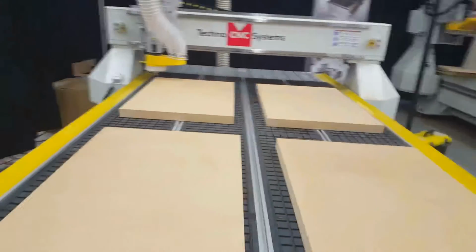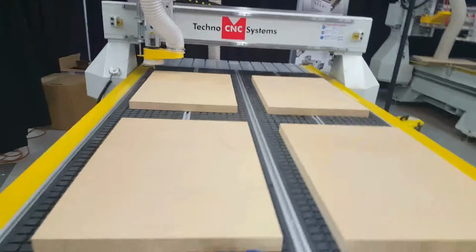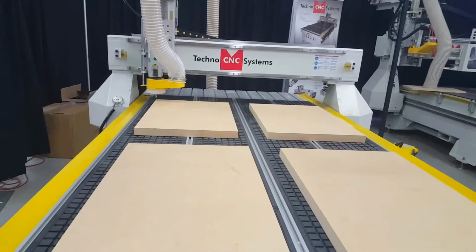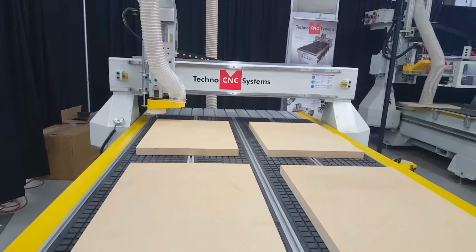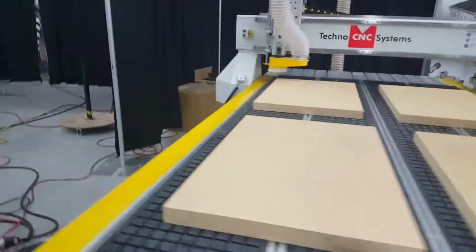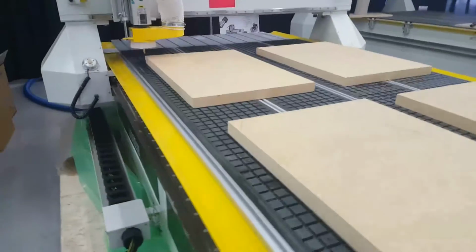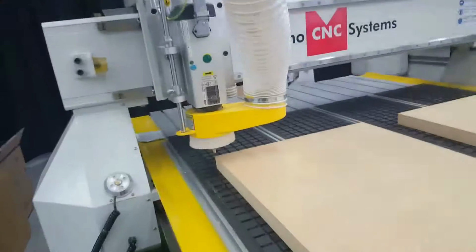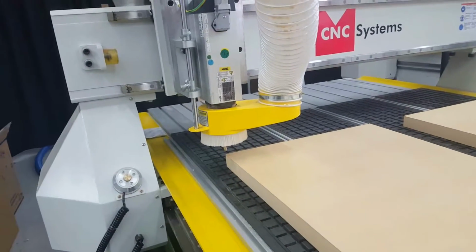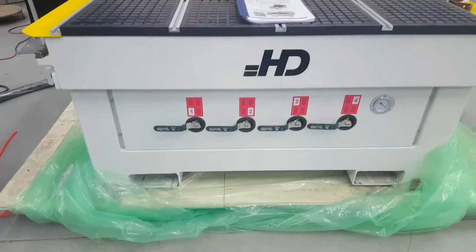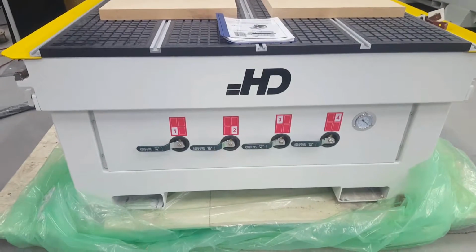The way that these pieces are set up is arbitrary to how you may set up your pieces. This is why when you get the machine, you must reset the positions at which your origin is going to be. For example's sake, I'm going to set my origin at the top left of each piece. As you can see, the machine is already positioned at that spot, and I'm ready to start saving that part. Now, each zone is labeled both on the vacuum table as well as on the interface.